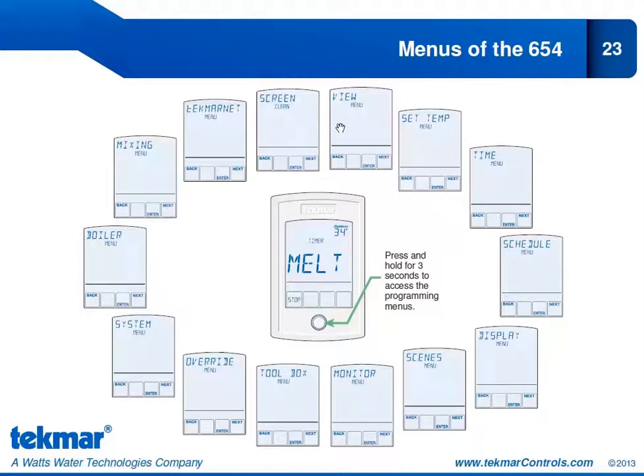Now we're going to go into discussion of most of these menus. Some of them I will not cover. I think the Time menu, the Schedule menu, Display menu, and Scenes menu are all pretty basic. If you have configured any of the TechMart thermostats or controls, and you're familiar with these menus, we won't go into them in this training webinar. Just like our Designer Series thermostats, you can navigate through the different menus by pressing and holding this button for 3 seconds, and you can scroll through the list of menus by hitting the next button key.